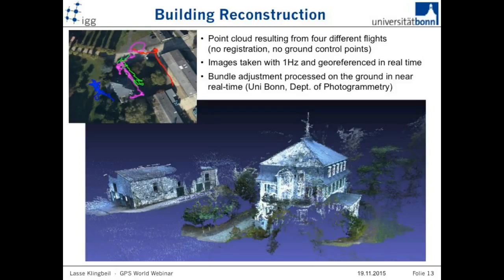It was processing the data, so that you can see during the flight already the point cloud building up, and they're all georeferenced. Each of the points actually has a global coordinate. Because we just threw all 4 clouds of the 4 flights into one bucket, let's say, you see that they fit together. You can't even see where the 4 clouds are. There's one border going through the house, but you nearly can't see it. So it shows that the georeferencing is working.